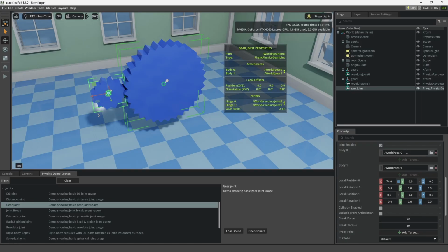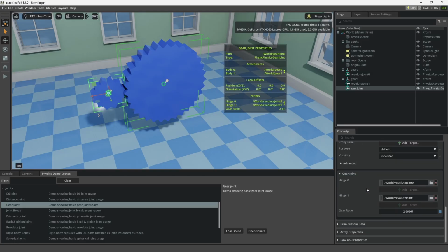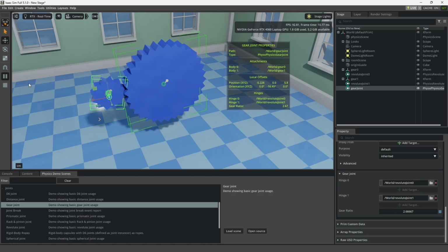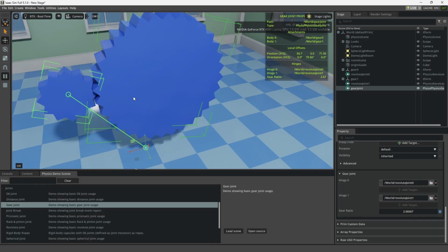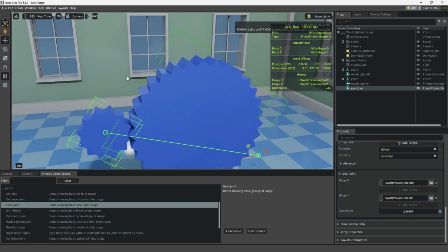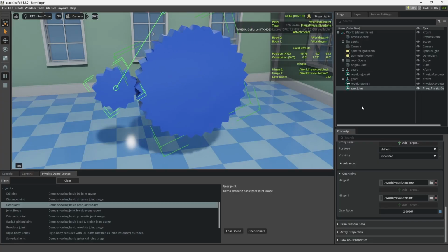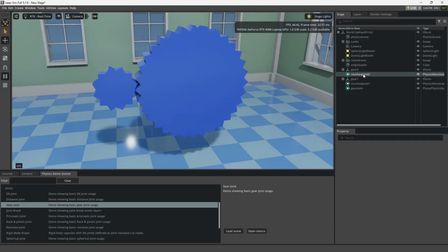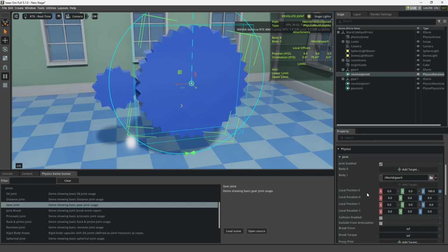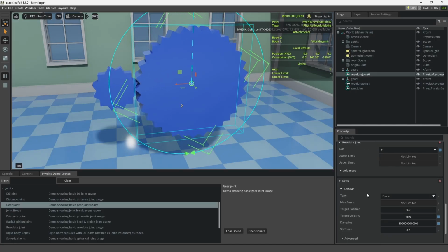And you can see world, gear 0 and gear 1, and then it actually hinges on the Revolute joint. So the gear joint has Revolute Joint 0 and Revolute Joint 1 with a gear ratio, so that when you hit play, they are connected. Now, one of the things about this is the simulation aspect of having the teeth do the driving. For example, let's see which one of these has a driver on it. This one does.